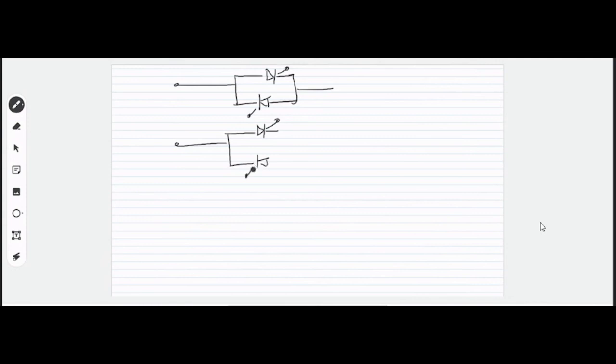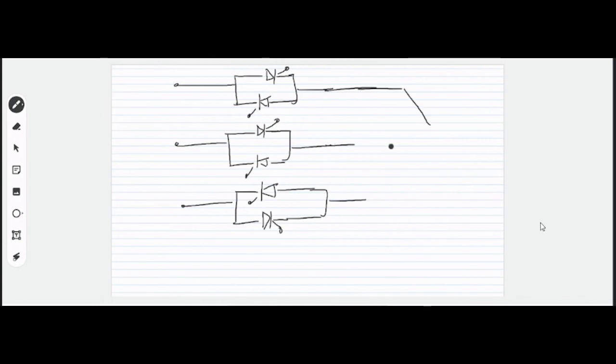Now how can we vary the stator voltage? The simple way is to use AC voltage controllers. We all have studied AC voltage controllers. These are anti-parallel connected thyristors or control switches. If we have a three-phase motor and we want to control the speed, we want to control the applied voltage. How can we control this? We can control it by feeding it through the AC voltage controller. Can we control the applied voltage?